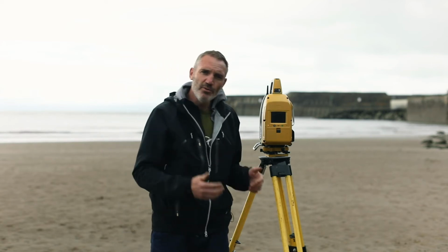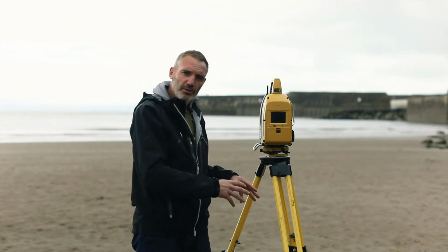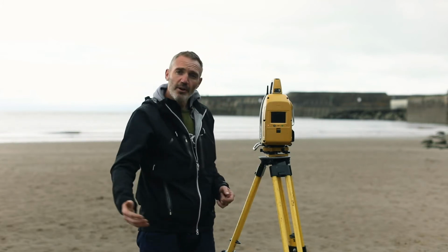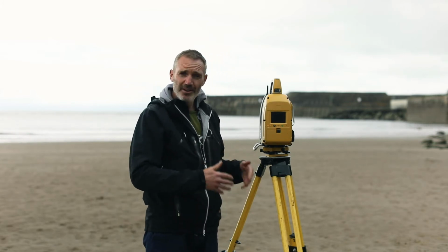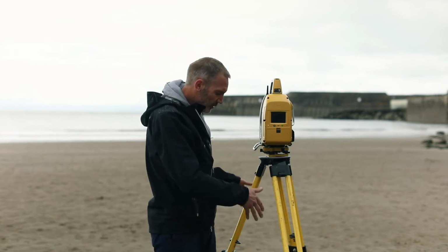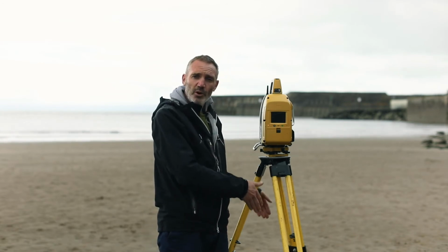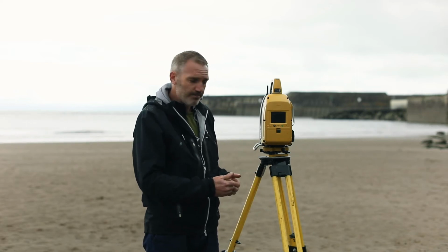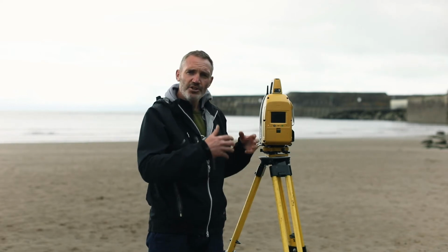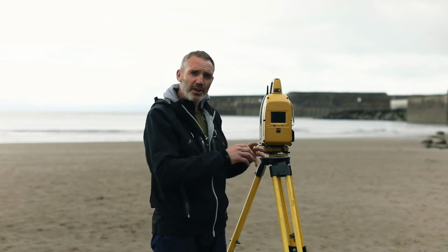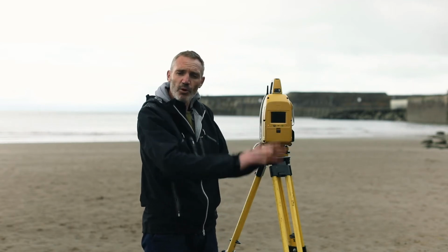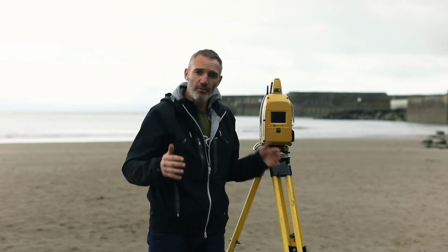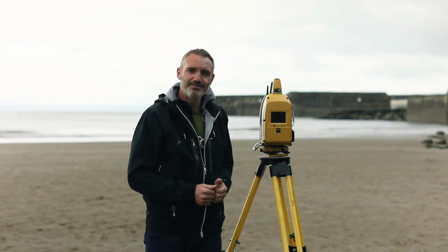If we didn't know the coordinates, if we were working on a local survey grid and wanted to change them afterwards, then we could bring an accurate differential GPS and measure our known points afterwards and put them on the OS or latitude and longitude grid. That's how we geo-reference our scans, so we can relate this structure, this seawall, and the aspects of this beach to the map of the country or the map of the world.